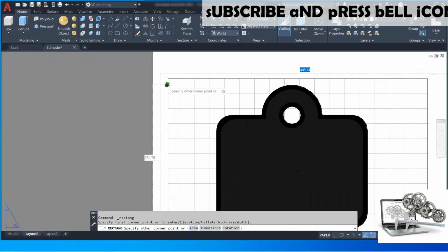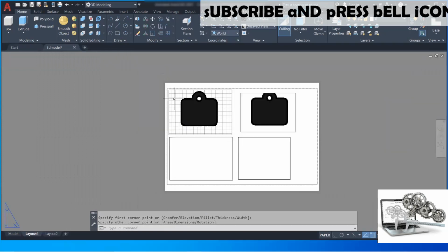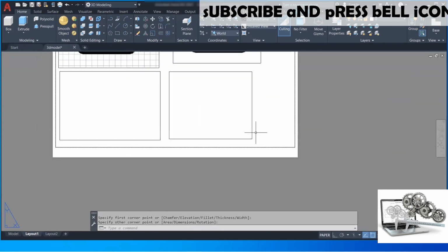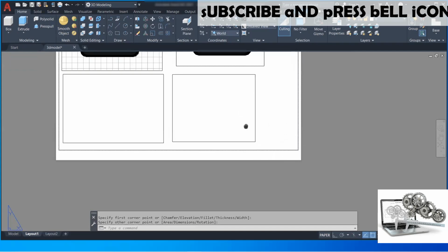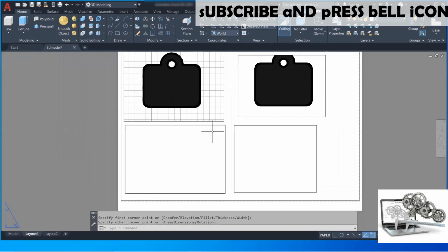I want to show the title block also, so we are creating one rectangle here that will act as a boundary for my entire drawing. Here you can give a little rectangle by using the rectangle command, and that will act as my title block.